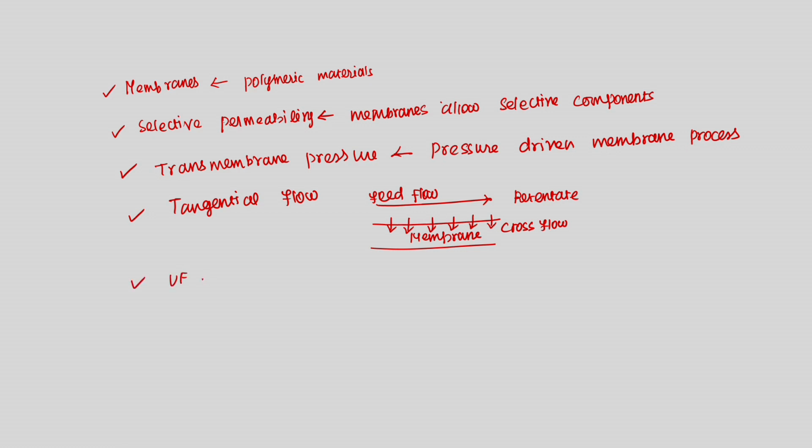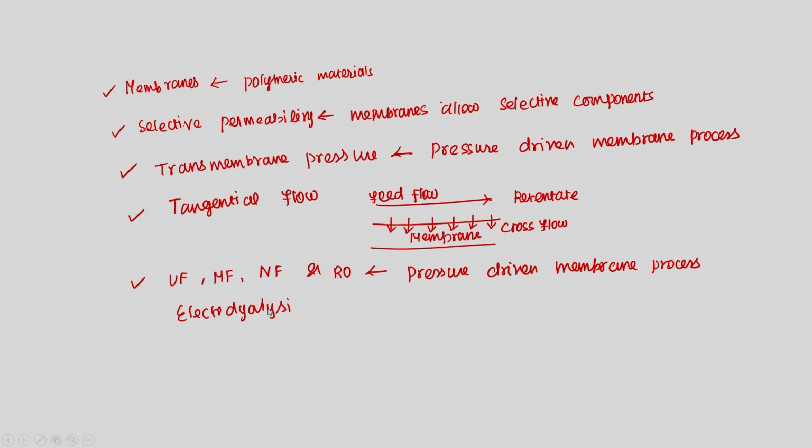These were a few important terms we have discussed. Whatever we are going to discuss, ultrafiltration, microfiltration, nanofiltration and reverse osmosis, all of them are pressure driven membrane processes. And we are also going to discuss electrodialysis, which is electrical field driven. That means the driving force there is the electrical field.